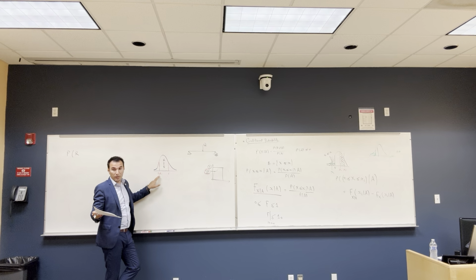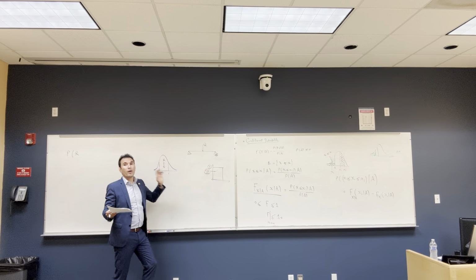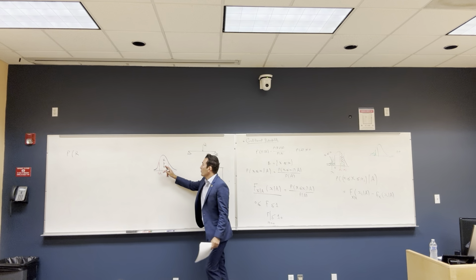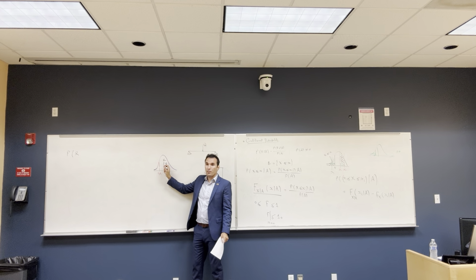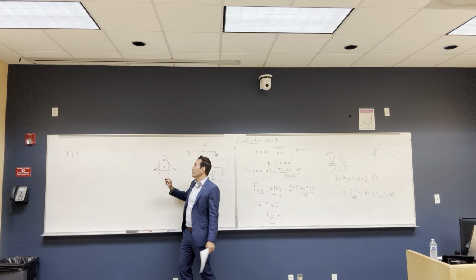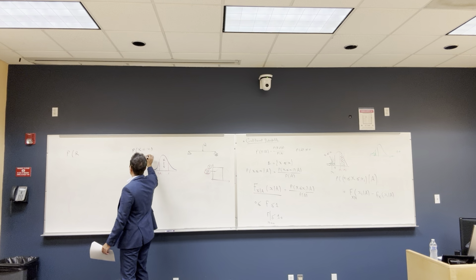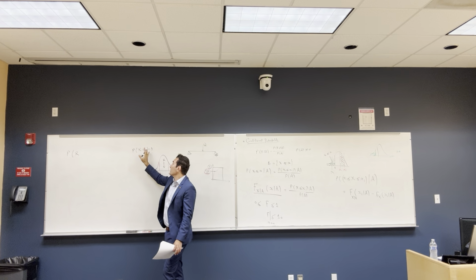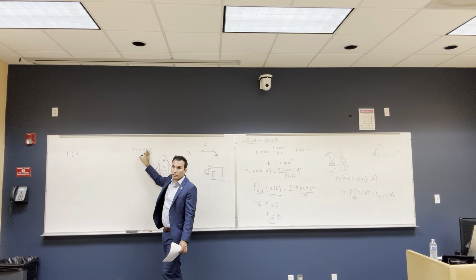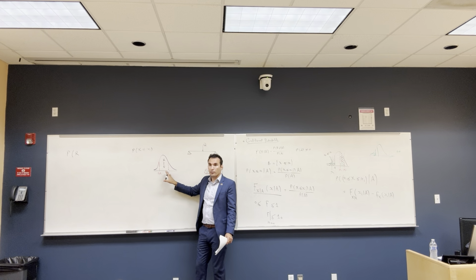We already took the beam to the test, and we tested the beam, and we know what the proof load is. And what's the capital R? Capital R is the random variable, the R that you don't know. If we knew it, it would be the small r here, but we don't know it. Do you remember when we say what is the probability of X less than or equal to small x? X is the random variable, and this is the assigned value. What is the probability of your wind speed to be less than 30? So here, what is the probability of your capacity load to be equal to this value?